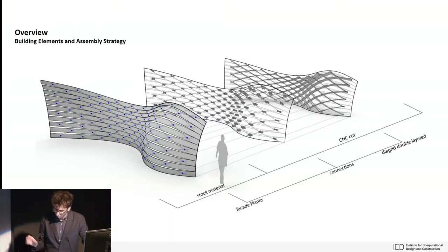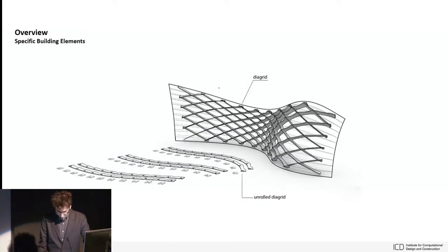It's basically this idea brought into a certain facade system, a certain facade structure, where you have a prefabricated substructure, but then you put cladding on it that is actually just stock material. So the idea is that the substructure is highly individualized, CNC cut, a diagrid basically, but the instructions on how to assemble it are already in a way engraved into these individual strips, and so the assembly of these strips is possible without having any plan drawings, without having any instructions.